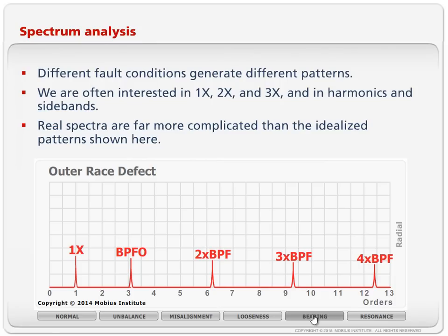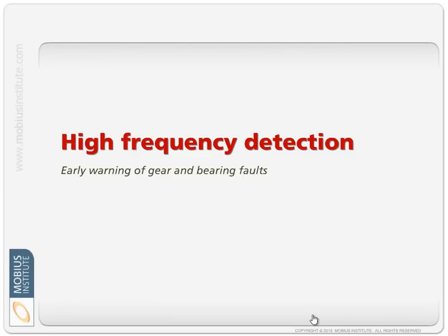Understand the machine, understand where the vibration comes from, understand the analyzer and sort of what you're seeing in the data, and then you can figure out what's going on and not just look at a wall chart and say, that spectrum looks a bit like that one, it must be looseness. That's the trouble. A lot of people get reports and it just says there's looseness, and I think, oh, what does that mean? What do I do? Anyway, another story. So that is basically spectrum analysis.